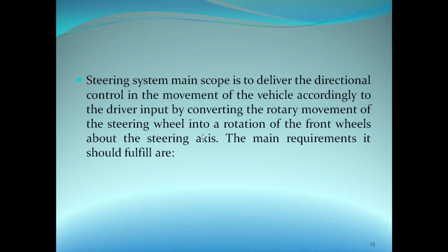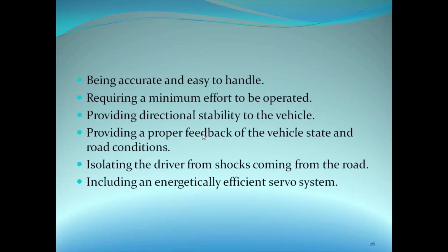The main requirements it should fulfill are being accurate and easy to handle, requiring a minimum effort to be operated, providing directional stability to the vehicle, providing a proper feedback of the vehicle state and road conditions, isolating the driver from shocks coming from the road, including an energetically efficient servo system.